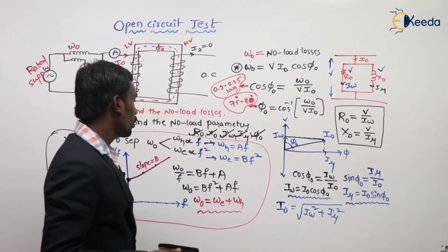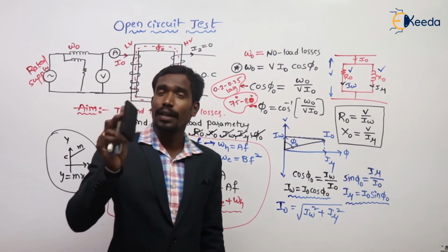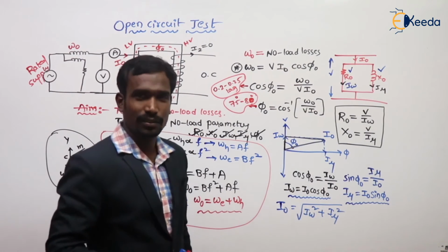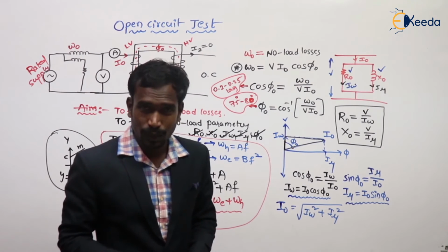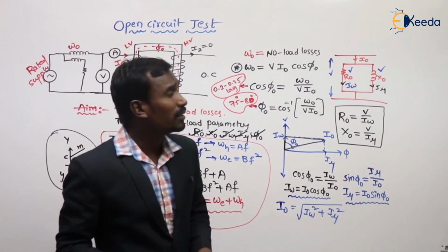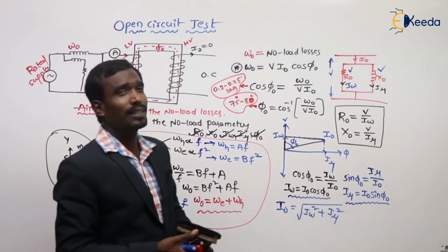From that, the no load losses are exactly equal to eddy current losses plus hysteresis losses. We can conclude that. Yes or no? Are you okay? Right? This is the open circuit test of the transformer.